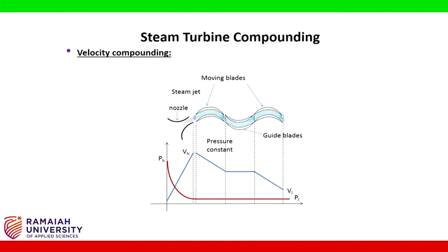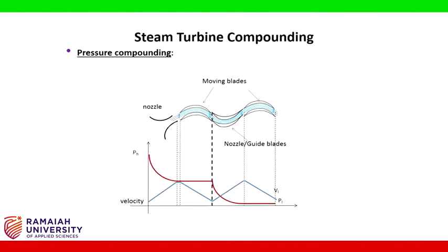decreases. Guide vanes are fixed to the casing and facilitate smooth exit of steam from preceding rows and smooth entry to successive rows to avoid losses. There is negligible loss in guide vanes owing to friction.